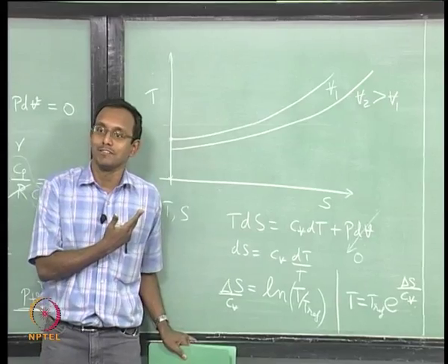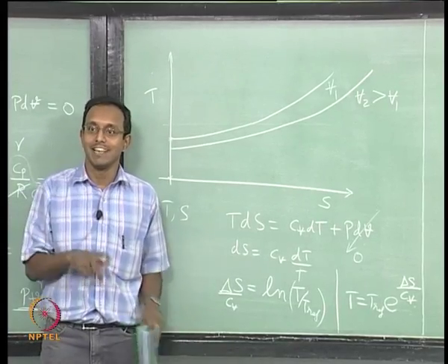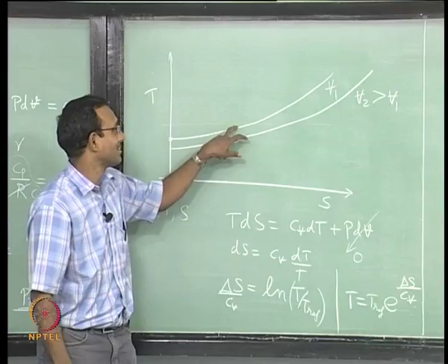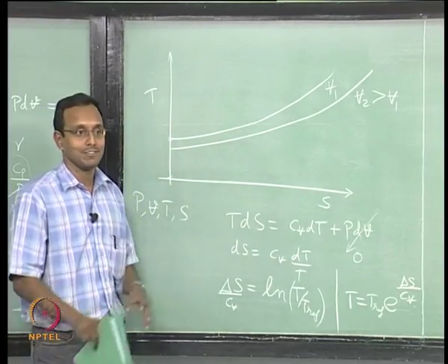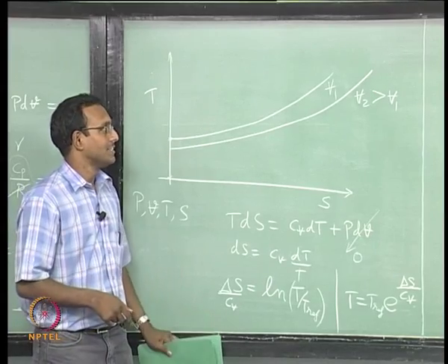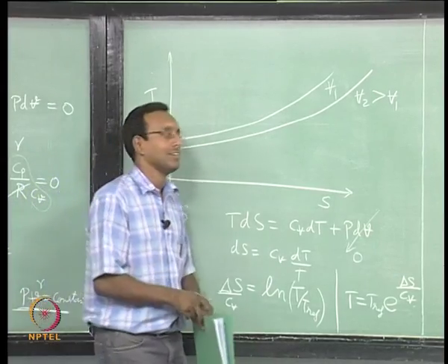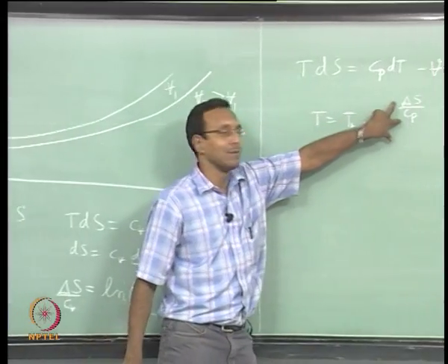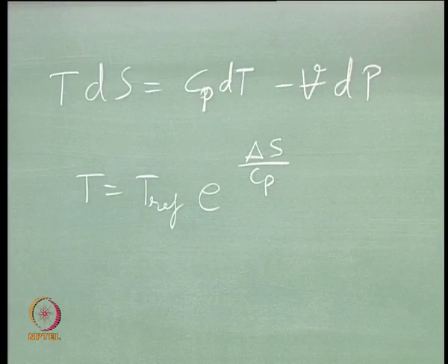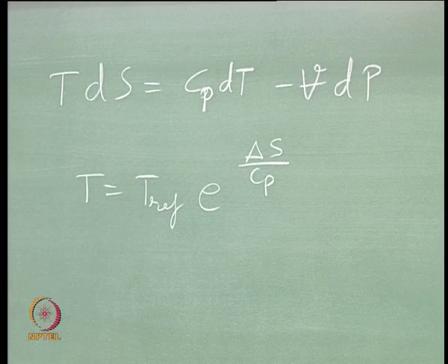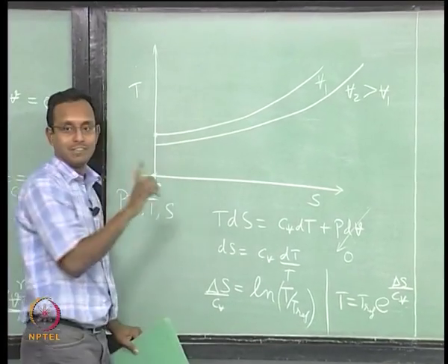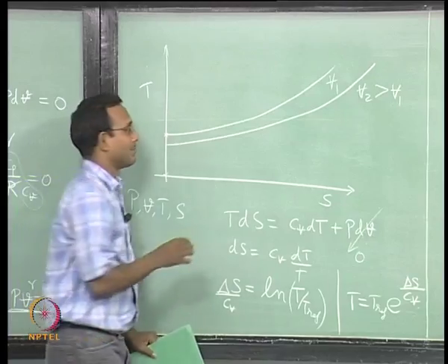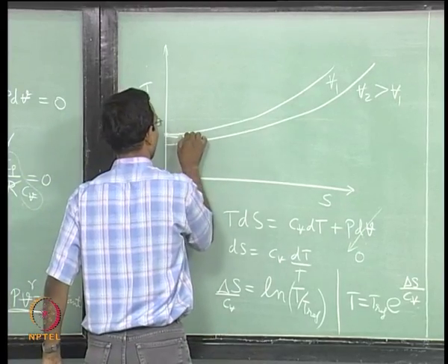This is again exponential, but I want to compare this curve and that curve, constant volume curve and constant pressure curve. Cp is higher than Cv, so the exponential factor will be lesser. So, temperature will be lesser for the given entropy. Okay. So, I have to draw the curve. It may start here, T reference and S reference are the same, but the curve will go different path.